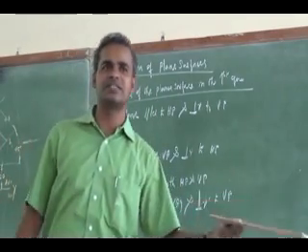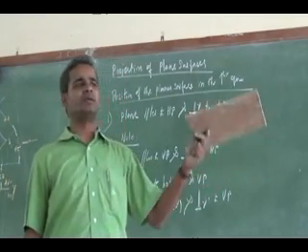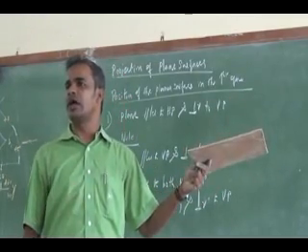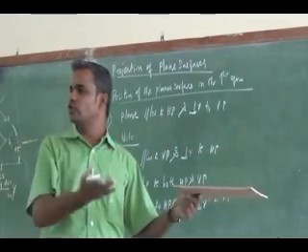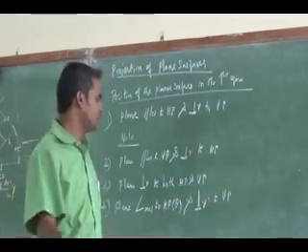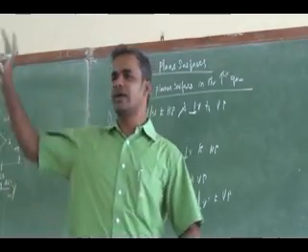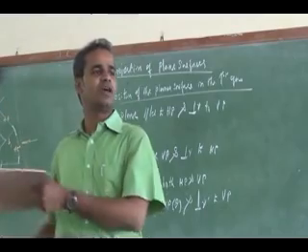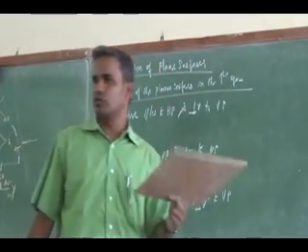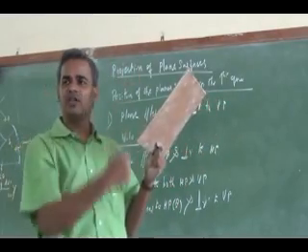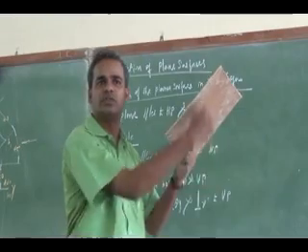The first step is the simple position step. I will be assuming the plane is parallel to the plane to which it is inclined. Then I can draw the true shape and project the front view, like your first problem. Then in the second step I can tilt the front view and get the final top view. Right, is it clear? So where will I obtain the true inclination of this plane?